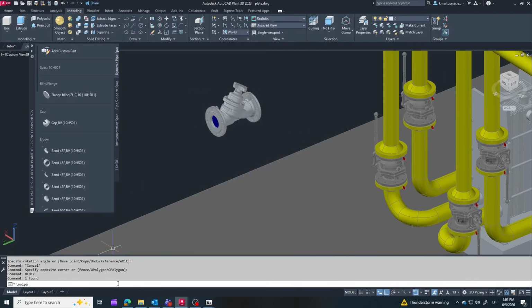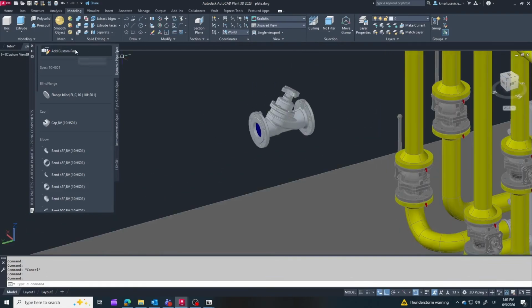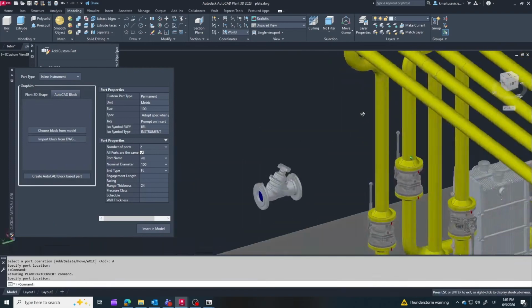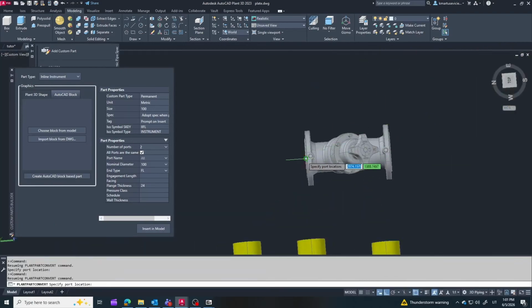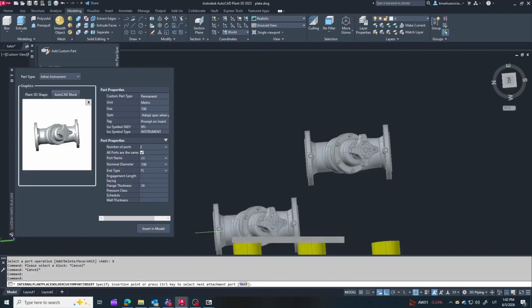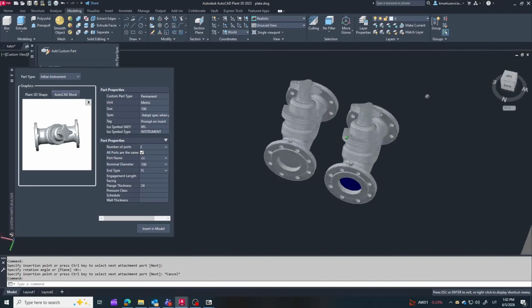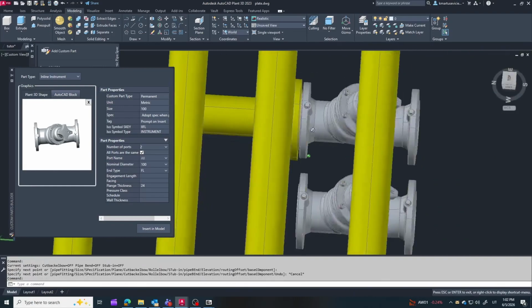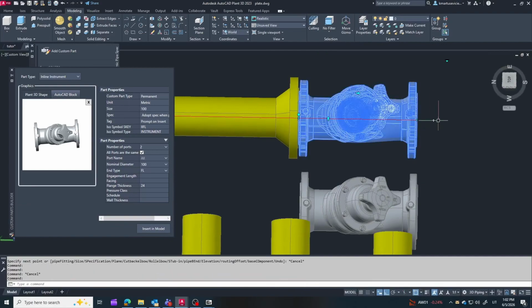Now, I'm converting the balancing valve into a live model and dropping it directly into the outlet line, right underneath the isolation valve. In this specific project, we only have a single heat exchanger setup. However, I really wanted to include this component to highlight a critical engineering concept. Remember, you use a balancing valve whenever you need to balance the flow across several units standing in parallel. Showing it here prepares you for larger, real-world industrial layouts.